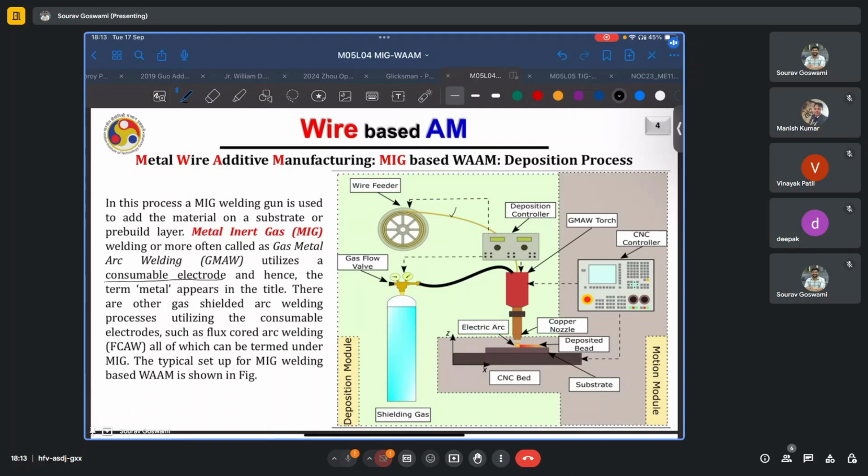However, in certain cases, such as when the amount of energy being transmitted is really high, or for some other reason the air surrounding the wire becomes conductive, then rather than going through the wire itself, the electricity can also flow through the air because of ionization. So the air becomes ionized, the electrons start moving freely, and this rapid and almost free movement of electrons provides an easier, less energetic path, that is a path requiring less energy, for the current to flow. Thus, the current can in fact flow through the surrounding air, and that is what is called an arc.